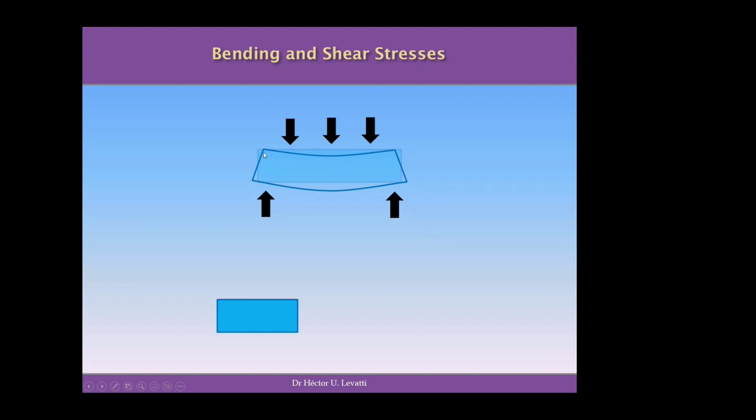So you can intuitively understand as well, seeing here on the figure, that you have shortened the fibers on top of the beam, because this length in here will be shorter than the original one, as you can see. And at the bottom, you are extending the fibers. So intuitively, you can see that in the bending process, there is a more complex behavior in terms of, let's say, the movements of the cross sections, producing this combined effect of compression and tension at the same time. And this is the basic difference between axial stresses and bending stresses.